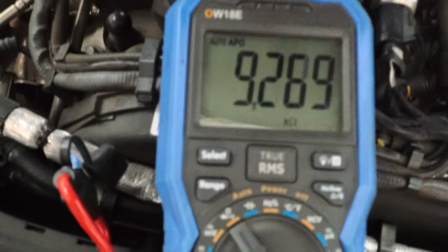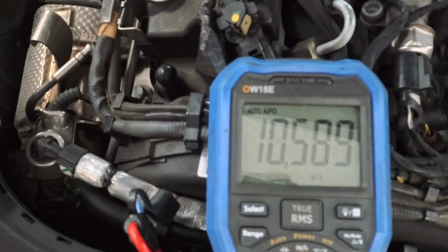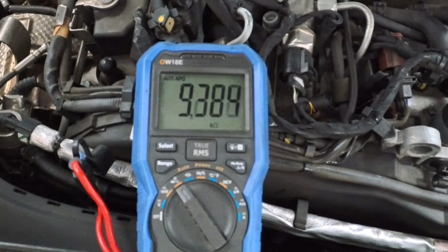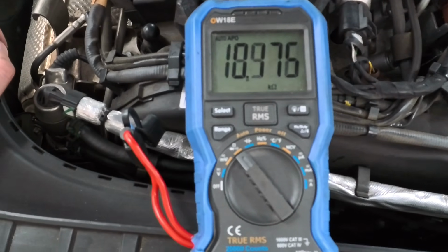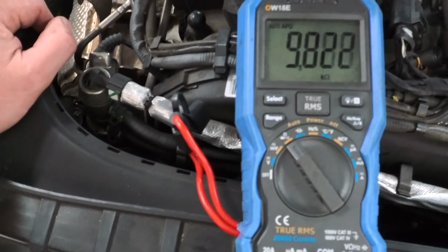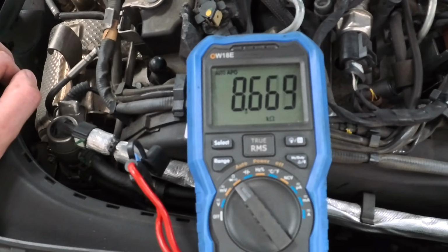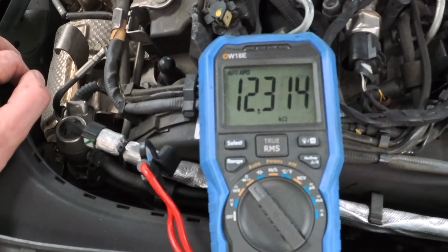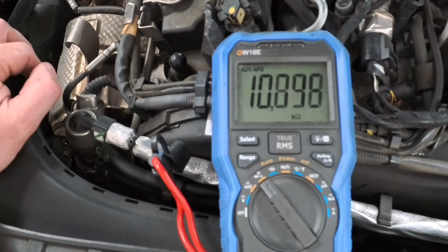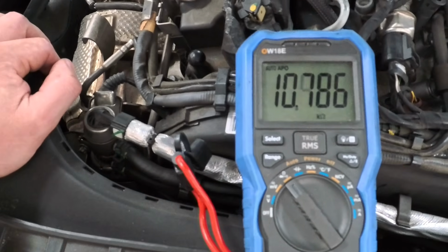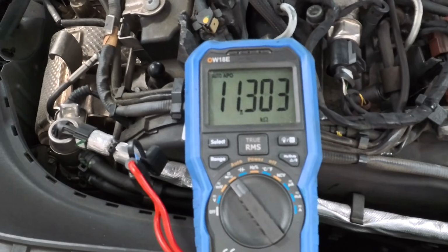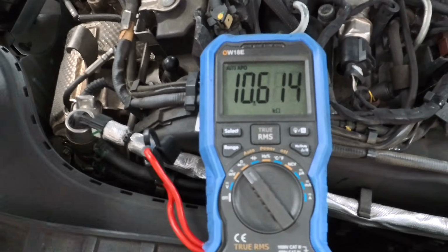Now what we've actually got is nearly 9,000 to 10,000 ohms. So there's so much resistance running through that component that it's registering as a circuit failure. Our recommendation to the customer is that we're going to need to replace that solenoid valve. Once we've replaced it, we can double check the rest of it and make sure it's okay, but that will definitely rectify that issue. After that, we can potentially move on to the DPF issues that she's got. So yeah, happy days.